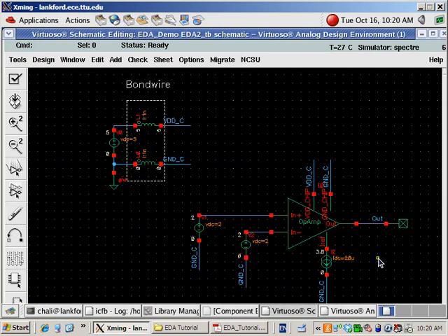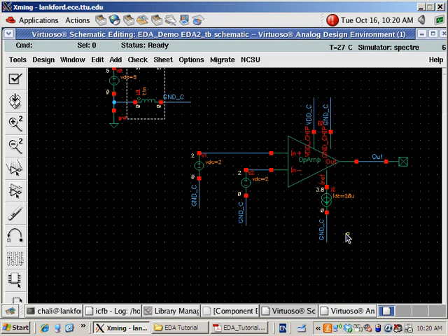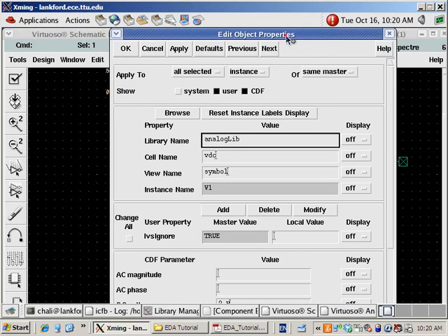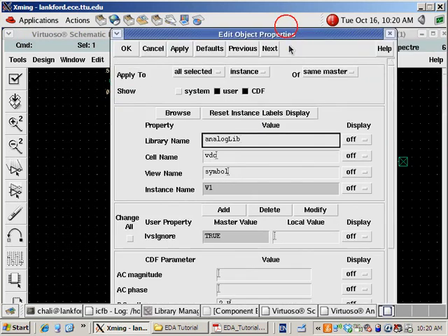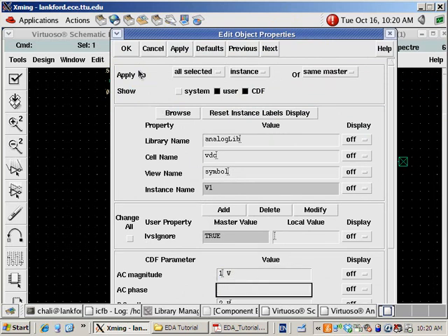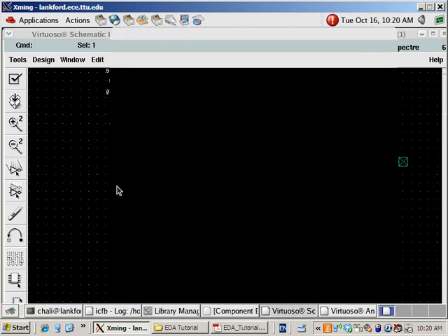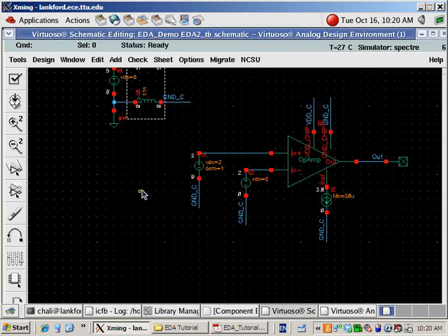Okay. All right. Sorry, before we add a feedback loop, we can do another thing. At the input side, for positive in, for this signal source, we can add an AC input of 1 volt. So that means for this signal source, we not only have a 2 volt DC bias, but we also have a small signal in AC as 1 volt.